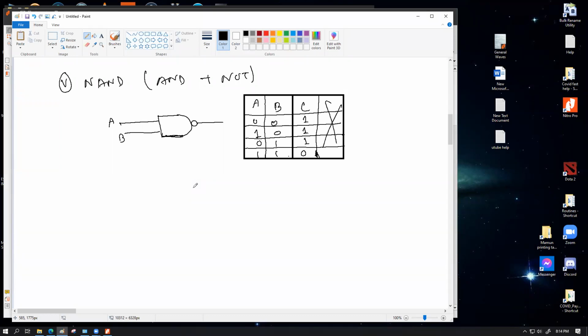And then G3 is going to come into action. G3 has 2 inputs. One is B and the other one is Z. So G3 is going to function with 2 inputs, B and Z. The shape tells us this is an OR gate. So what was the value we got for B? What is the value for B? So 1. And the input we are giving at Z is 0. Now an OR gate, whenever it is fed 1, 0, gives us 1 as output, because if either of the inputs is 1, it gives us an output. That means C will be 1 here.